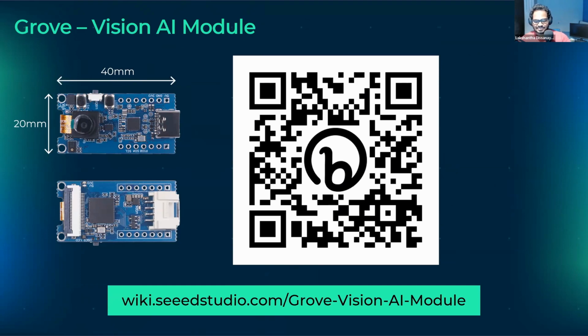So we have this one. You see this kind of board. It's a very, very small board. This Arduino Xiao, you can directly connect with the Grove Vision AI module, which has a 7-pin dual row connector. So this one can directly be on top of this one like this, and this will be a ready-to-go solution just like this. You don't need the WIO terminal in this scenario, because this can connect with the Arduino IDE, and then it talks with the Grove Vision AI module.